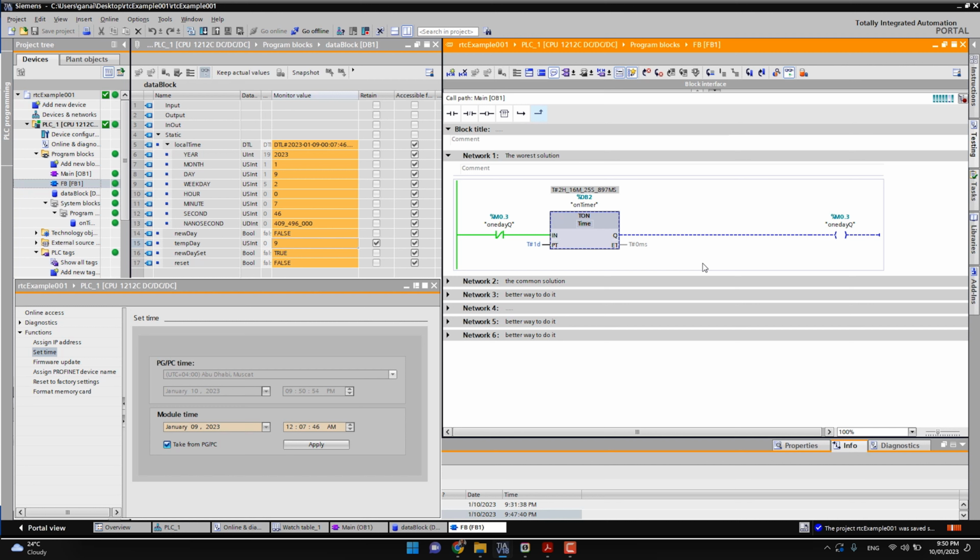And here, basically, our friend has no idea that we have RTC, or he never thought about using it for these triggers. And there are two issues with this approach. The first one is we don't know exactly when this trigger is happening, which would definitely impact your data visualization. The second issue is that if the PLC is off for any reason, then this timer will reset and start counting again.